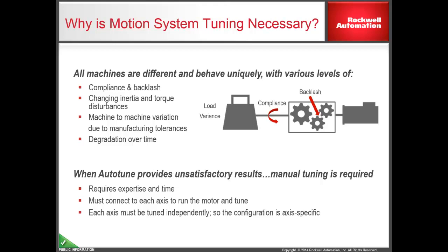Tuning methods and tools, such as the auto-tune function, currently exist to simplify the tuning process. However, the wide range of application types makes it very challenging to develop a simple, all-encompassing method for tuning. As a result, when the auto-tune function provides unsatisfactory results, manual tuning must be used, which often requires knowledge of advanced tuning techniques. In addition, manual tuning is applied to each axis independently, so each axis acquires a different tuning configuration.